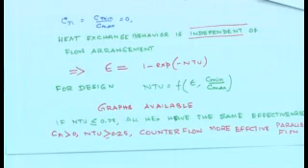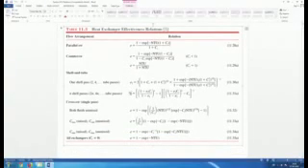So what I show you here is from the text, there are certain relations and correlations which can be seen for the case of parallel flow, for the case of counter flow, shell and tube with one shell pass and multiples of 2 in terms of tube passes, n shell passes, and if you have 2 shell passes then there must be 4 tube passes and so on. In cross flow, then all exchangers for which CR is equal to 0, which is the case for condensers and for boilers, the relation between epsilon and NTU are provided in the text.